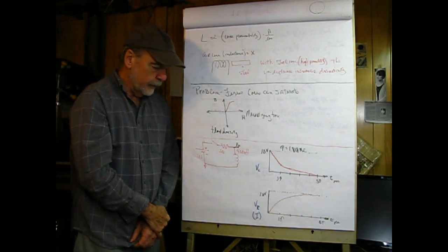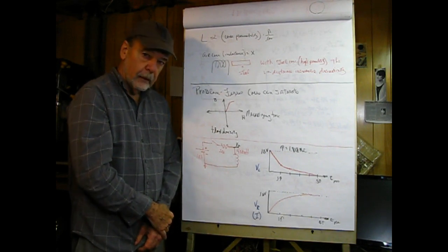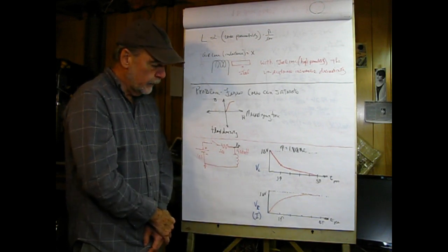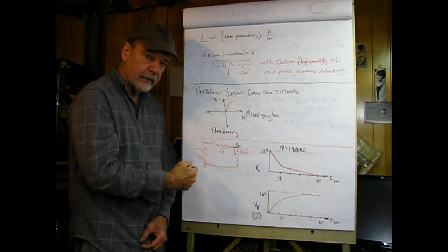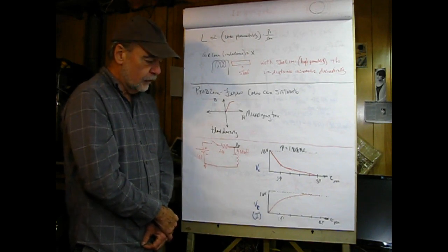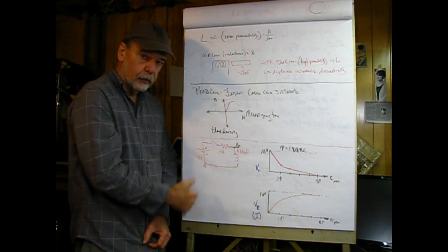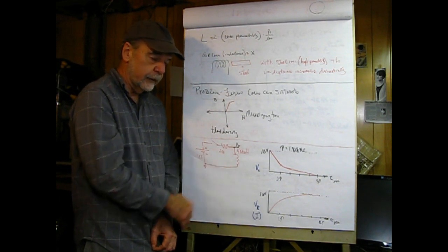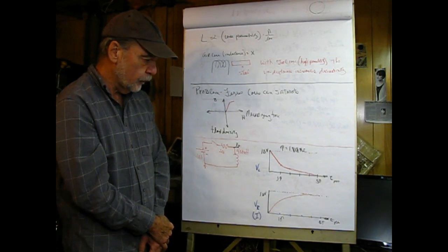So let's take a look at the charging waveforms here, and what we have to do in this case, like with the capacitor, is we have an initial condition. When we talked about capacitors, we said that the DC voltage at time equals 0 and charging would always be equal to 0 volts. Now the same is true with an inductor. We're going to say that there's no flux in it prior to closing the switch. So that makes our calculations a little bit easier in an inductive circuit, other than most supplies that typically would not be something we're going to consider.